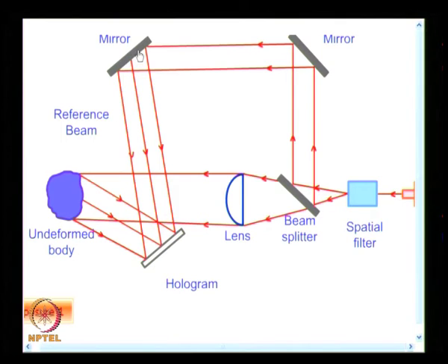The whole approach was processing the intensity information. The approach is not just looking at fringe order and then assigning it. You have to look at what is the intensity at the point of interest. By processing the intensity information, they were trying to find out fringe order at every location. And in all those experiments you have only one phase, that is the phase difference because of deformation, and in order to get multiple images the usual procedure was to move this mirror in known steps, and they also used piezoelectric actuators to do this.